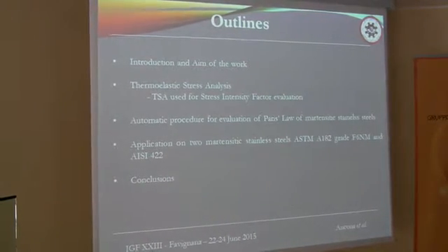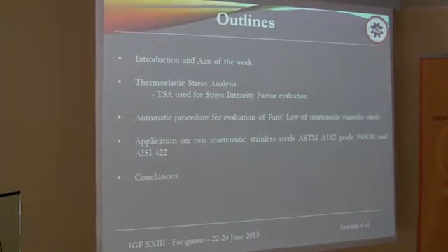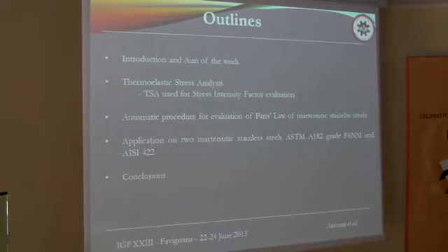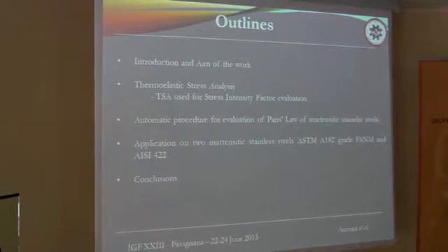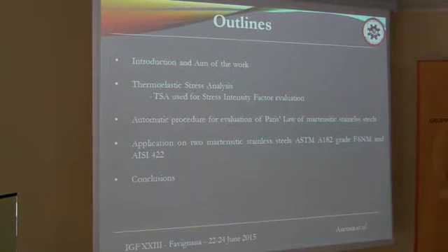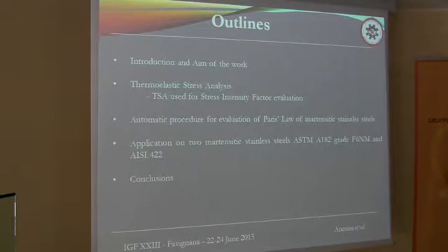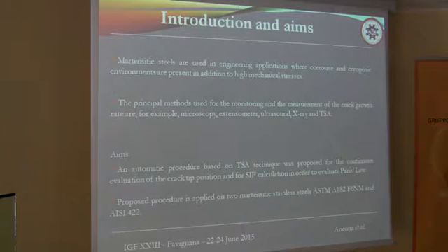The outline of this work is the introduction and the aim of the work, the thermoelastic stress analysis, in particular used for the stress intensity factor evaluation during fracture mechanics tests, the automatic procedure proposed for the evaluation of the Paris law, in particular in martensitic stainless steels, and this application onto martensitic stainless steels, ASTM A182 grade F6NM and AISI 422, and then the conclusion.